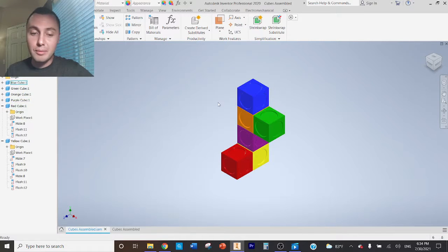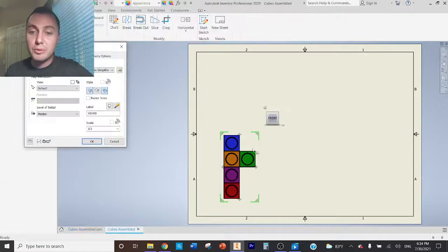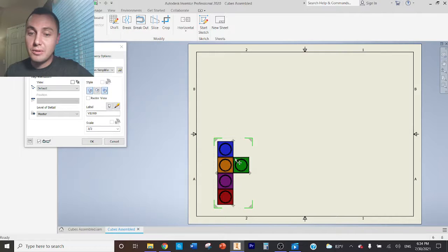All of these views are really important when we're doing multi-view drawings, or orthographic projection. Both of those mean the same thing. In the drawing here, I'm going to take that object and place each of the flat views, the orthographic views, and orient them so that if I were to send this to another engineer or a manufacturer, he could look at it and say, this is the front view, this is the right, and this is the top, just based on where it's positioned on my paper.